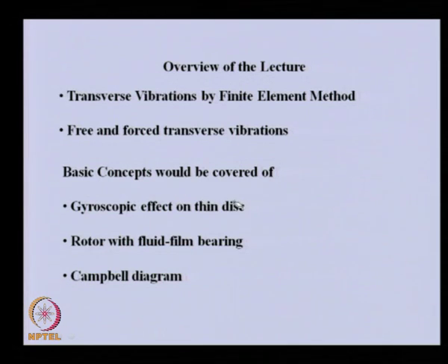We will not be considering the shaft gyroscopic effect, only the gyroscopic effect of the thin disc. Whatever properties of the shaft we considered earlier, the distributed stiffness and mass, will be incorporated, but we will not incorporate the gyroscopic effect of the shaft, only of the thin disc.